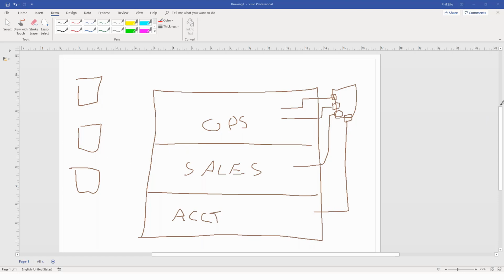Now, to answer that question, what determines the number of VLANs needed for a BAS implementing IP controllers? It's all about your architecture. So typically you're going to have one VLAN per, I would say, 128 to 256 hosts. Okay. Now, granted, you can assign the same VLAN, if I remember correctly, and I'm going back here on my memory.